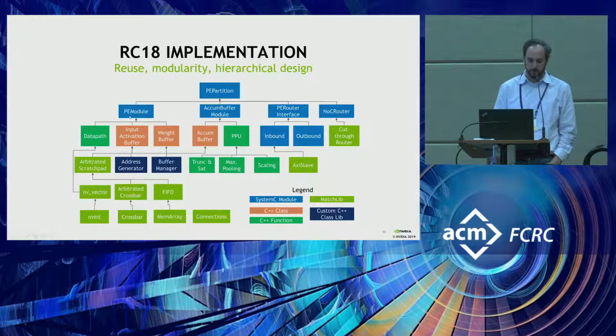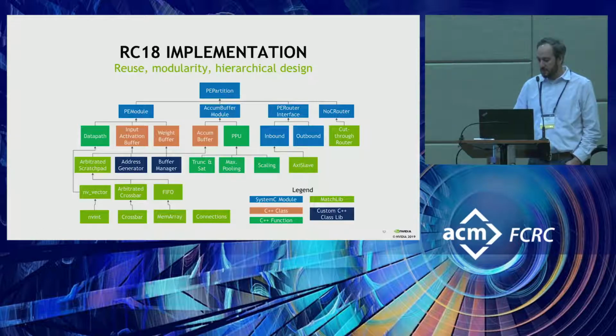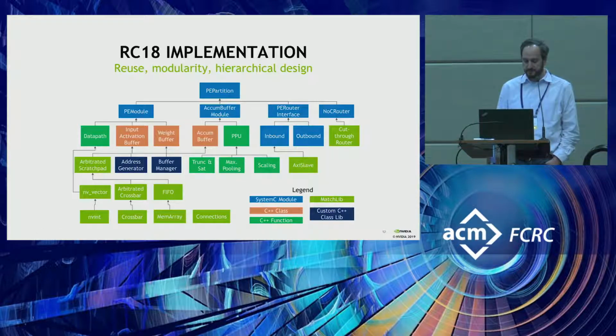For example, over here we have a data path class that implements the vector MAC dot products, the input activation buffer class that implements the streaming of the activations and so forth. So I guess the takeaway point is that we were able to achieve a lot of reuse, which was the original goal, modularity, and use hierarchical design to make this very productive.